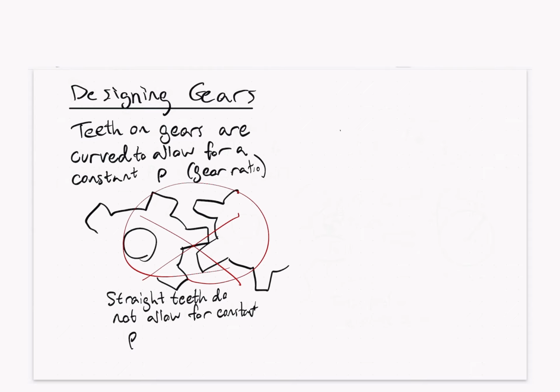So if we want to have that nice connection that we discussed in our previous videos, where we have two circles that are essentially connecting with each other, with some radius here and some radius here, and our points A and B can be represented by their interactions at point P, then what's going on is that we have these involute curves.